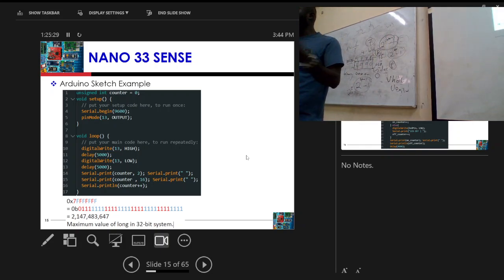You guys know that, right? You know analog pins. So it's taking signals from the environment and feeding them to the MCU. So those analog pins serve as inputs, while the digital pin serves as what? Output. So it means that you cannot connect a sensor to the digital pin, because the digital pin is supposed to give out a value, right? So I can connect an LED to the digital pin, so that I control the LED.